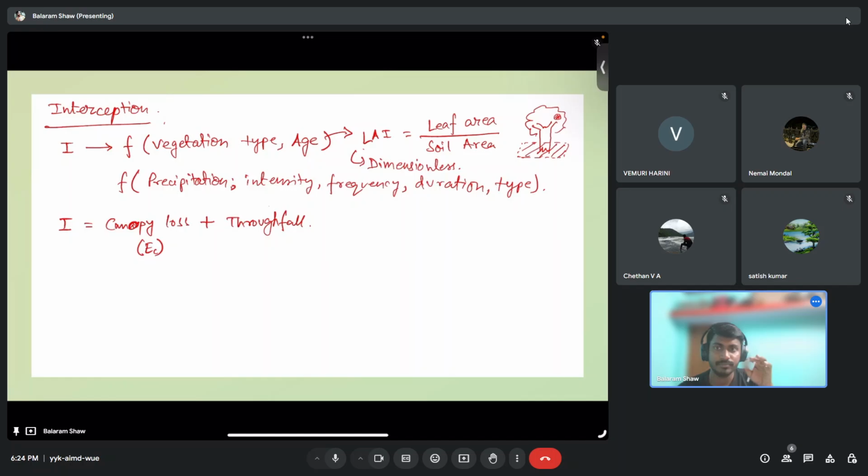Okay, and then from there we can get the forest floor litter, whatever interception has happened. And remaining is from the gross precipitation, throughfall and stem flow, we will get the canopy loss. So this gross precipitation, how do we get it? We put a rain gauge nearby the openings. So let's say if vegetation is here, wherever openings are there, we'll put one rain gauge there. We'll take the precipitation from there. That is called gross precipitation.